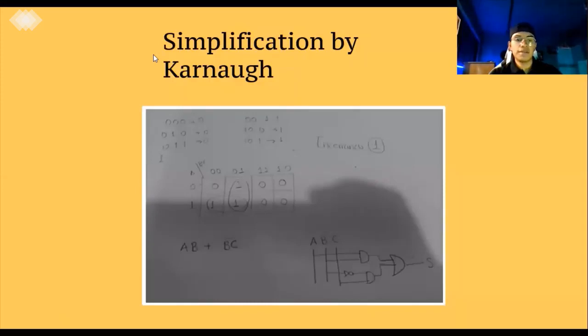With this, we can say that the equivalent reduced circuit is made up of a NOT gate, two AND gates, and an OR gate. This shows that the reduced circuit presents the same gates used in the original circuit implemented for this project.